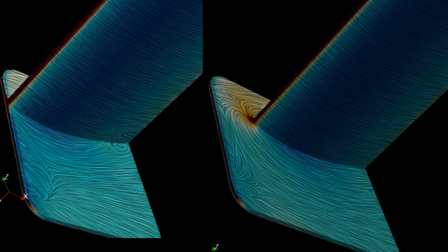Lastly, there is one observation worth noting. On the first extended endplate, there is a thing called two-wall separation. Apparently, having perpendicular walls in low pressure are more vulnerable to separation. Adding the forward extension to the endplate removes the separation. It would be a wild guess to give a reason. So in conclusion, the more endplates, the better.